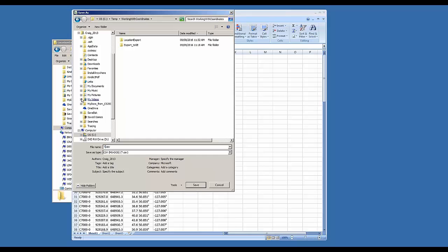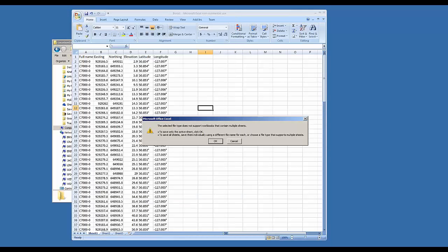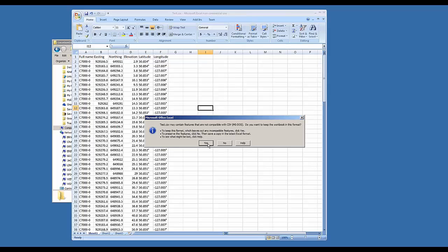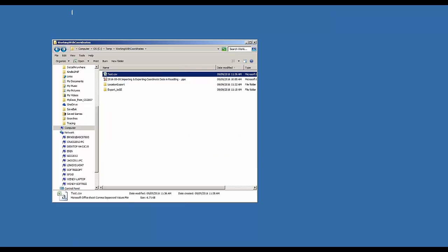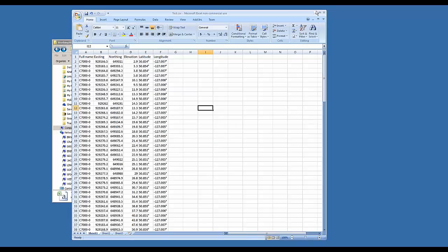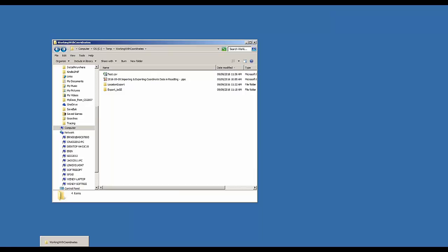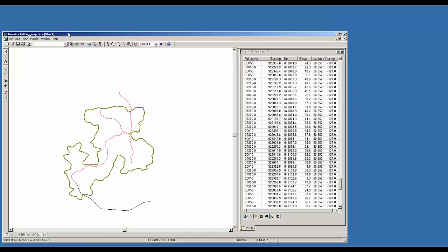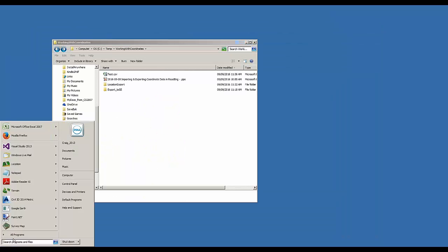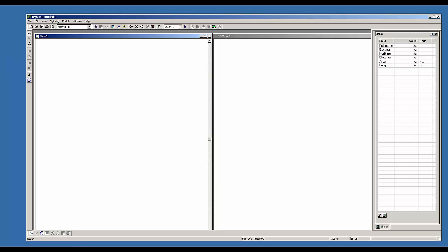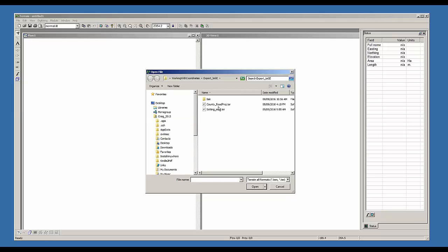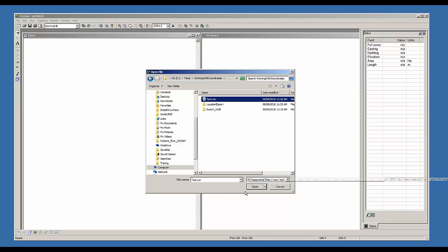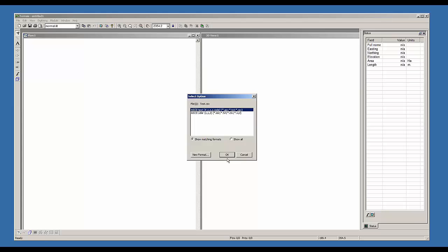directly into Terrain. This is how you would get total station data in. Pretty common. So there's a CSV file. Save it. And then come over here and we can read it back in. So there's the CSV file that I just saved. Close that. Start up Terrain. I'll start another instance of Terrain, be easiest. And I can go File Open, and I choose all supported files. I have CSV in my list. If I go to open that, it says it's a text file.